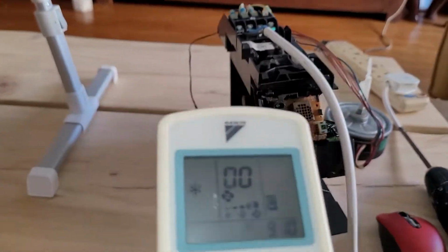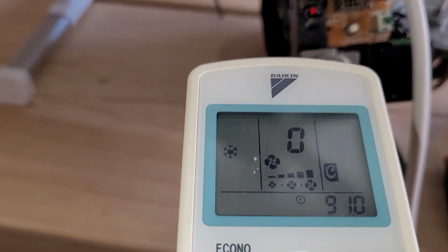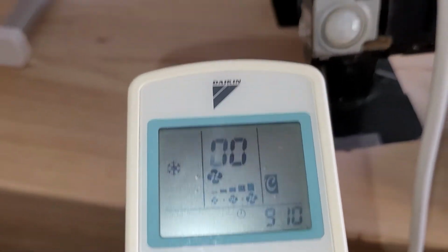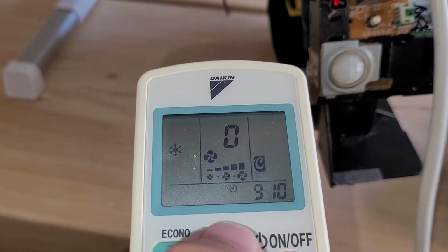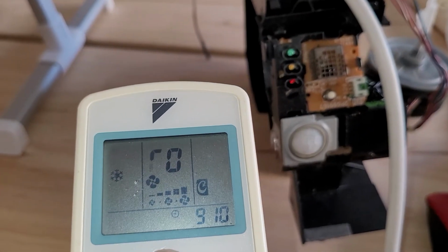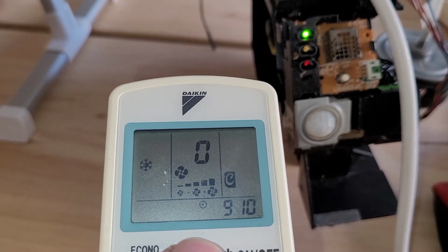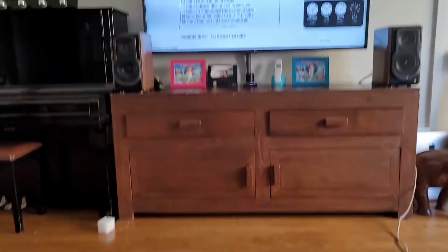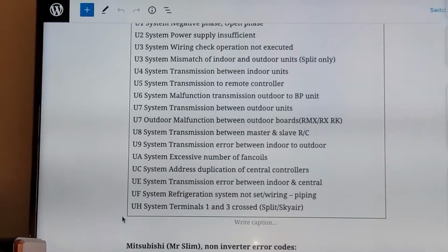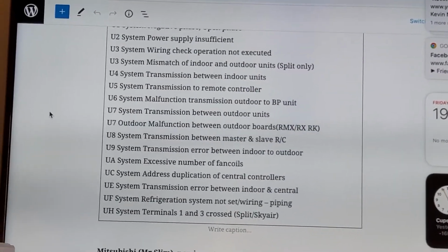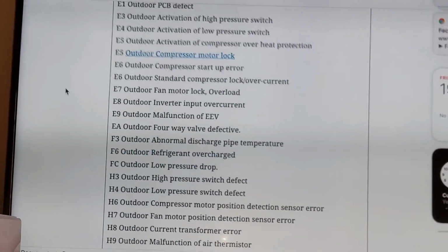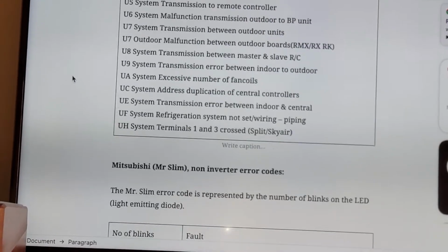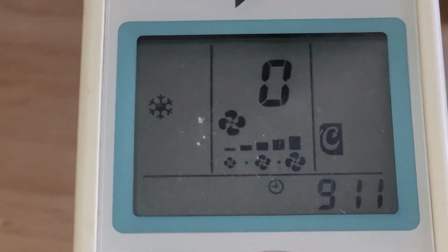What I'm going to do now is press temperature up or down, either way. Let's start with pressing the temperature up. You hear one single beep, right? Over here they actually have a long list of malfunction codes, as published on my website here. The malfunction code starts from A0 all the way to UH, so that's quite a lot. If you go through like this, you find that you need to cycle through quite a number of them. Let's anyway just do it.